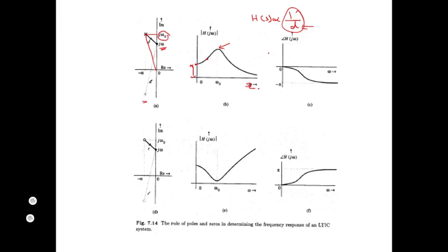And what is this frequency called? This frequency is called the resonance frequency of the filter, okay. At the resonance frequency, the pole will be having either the maximum gain or the minimum gain, okay, maximum gain or the minimum gain. You must have studied about this resonance frequency in the RLC circuits, right? So the same principle, either the resonance may increase the power or it may decrease the power. You're getting my point? So in this case, by applying the pole, it is increasing, and that highest point is called the resonance frequency.